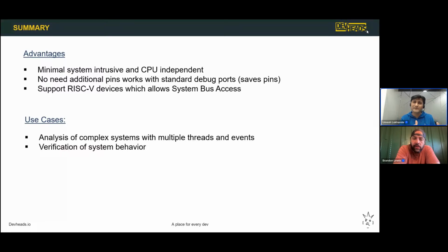When you build an application, you have some real-time requirements, and you have to make sure your application meets them. That can only be done by recording and analyzing the traces, and analyzing at what milliseconds or microseconds your task executes and what happens in the microcontroller. And then you can optimize the resources and the performance.